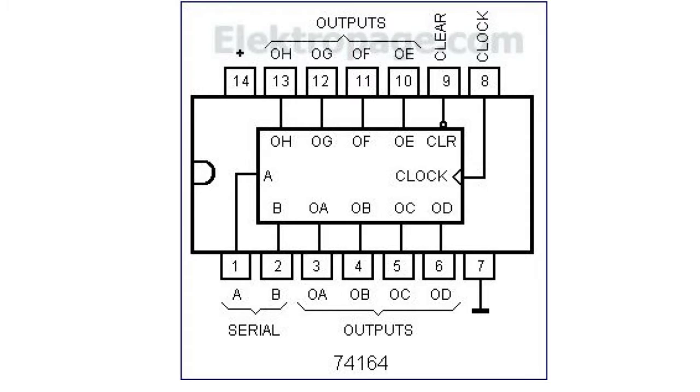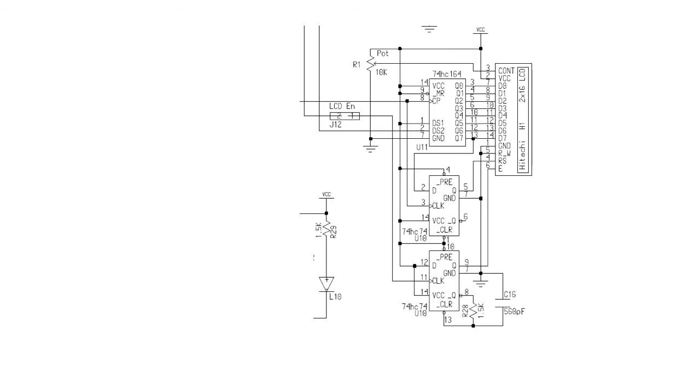So here's a little shift register. It's got a serial input, and it's got parallel outputs, and it's got a little clock. You could use the serial clock for that. And so this would be a perfectly fine slave for an SPI interface. And here's a way in which you could configure the SPI interface, giving us data for the so-called Hitachi LCD display. And this is one of those things that has, I would say, just a little bit more detail than you need, but it's interesting to see how they've gone about implementing this.